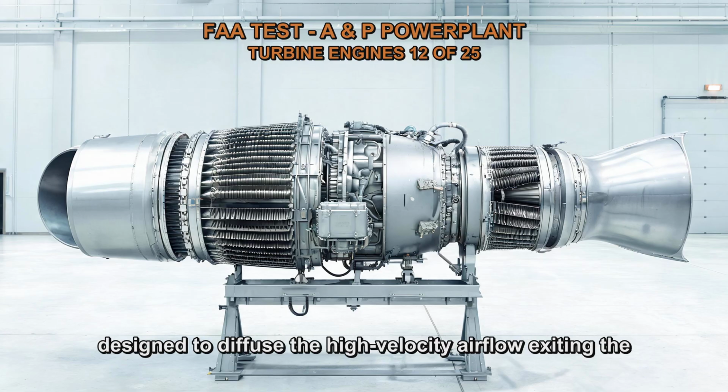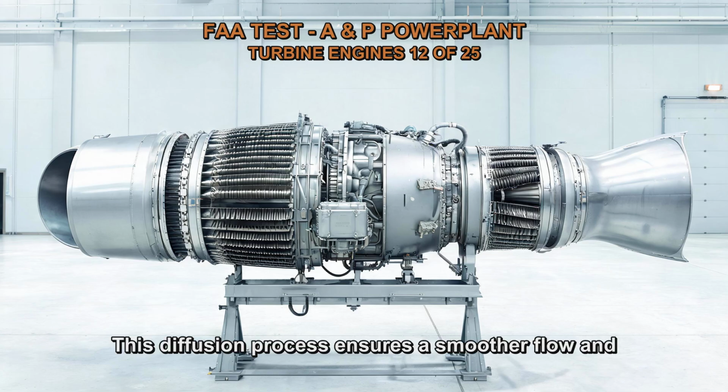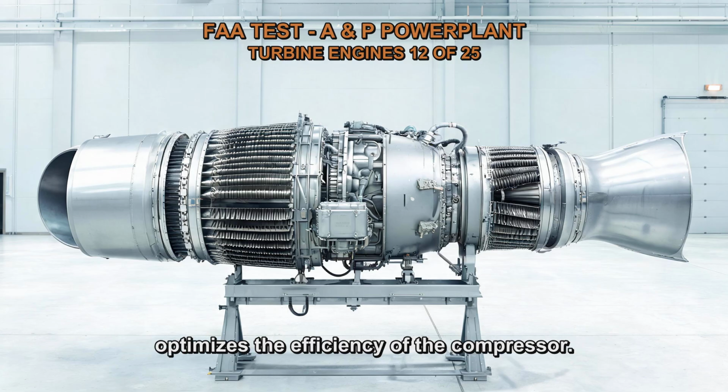The stator blades are designed to diffuse the high-velocity airflow exiting the previous row of rotating blades. They help to slow down and redirect the airflow before it enters the next row of rotating blades. This diffusion process ensures a smoother flow and optimizes the efficiency of the compressor.